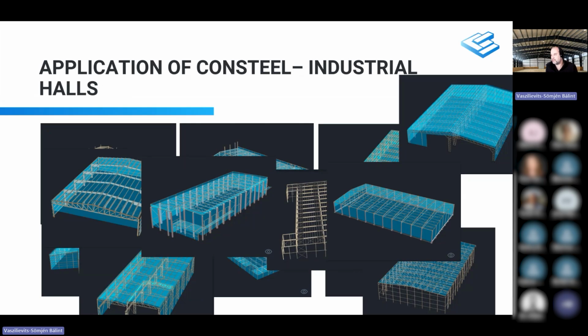Imagine if you have a multi-story building, it's relatively easy. You have everywhere columns, which are anyway carrying huge axial loads. The building itself is usually stabilized by shear concrete walls around the elevators or staircases. So basically the steel columns are just pin structures or more or less close to a pin configuration, and they mostly carry vertical load.